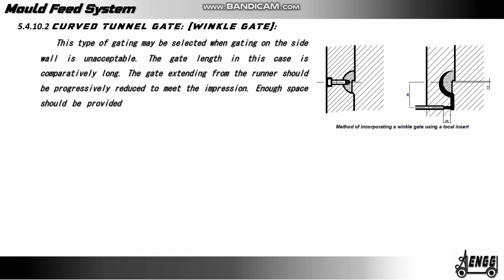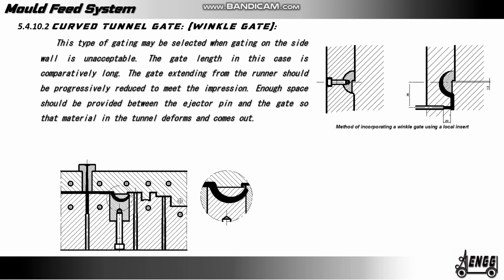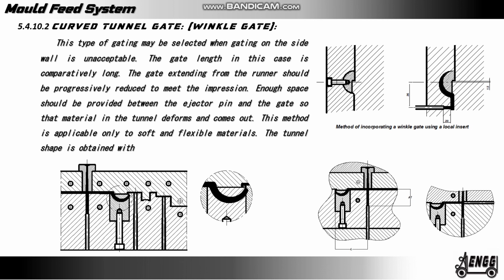Enough space should be provided between the ejector pin and the gate so that material in the tunnel deforms and comes out. This method is applicable only to soft and flexible materials. The tunnel shape is obtained with a lock insert.